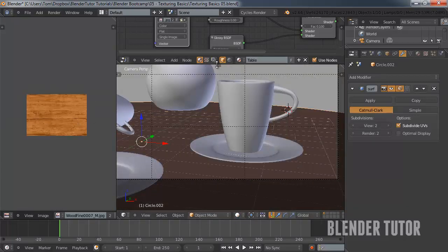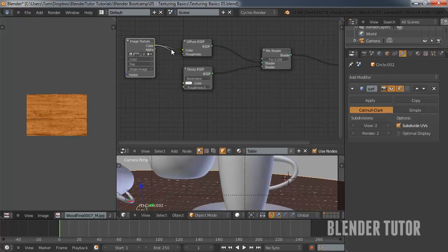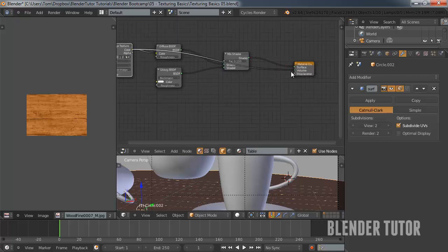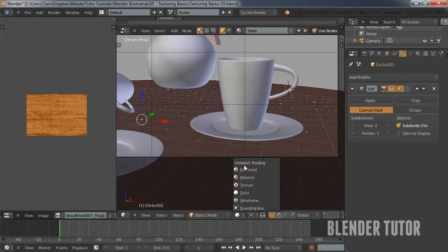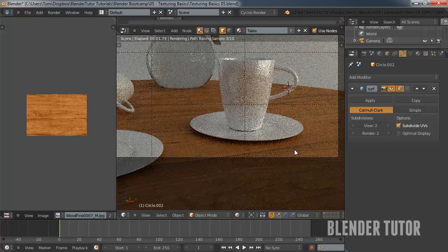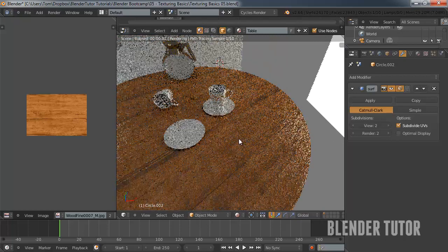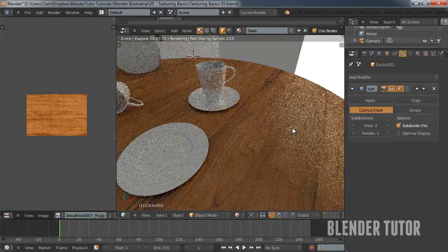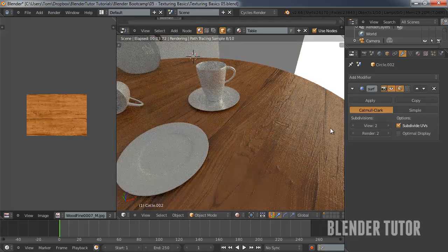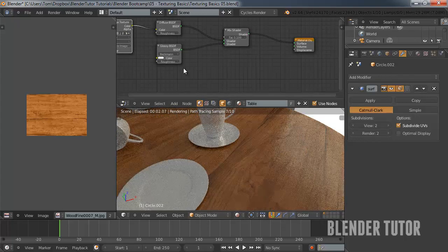we'll go into our material again, and you could really just take this, and here, we'll take our texture and stick it in displacement. And now if we look at it rendered, you can see it's got some bumpiness to it now. Seeing the reflection there, you can see basically all the 3D lines of the wood, whereas before, if I take that away, it's just perfectly flat.